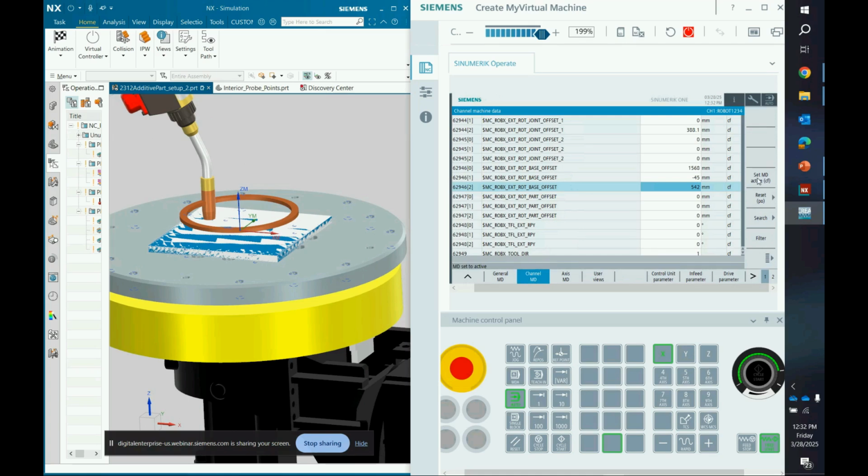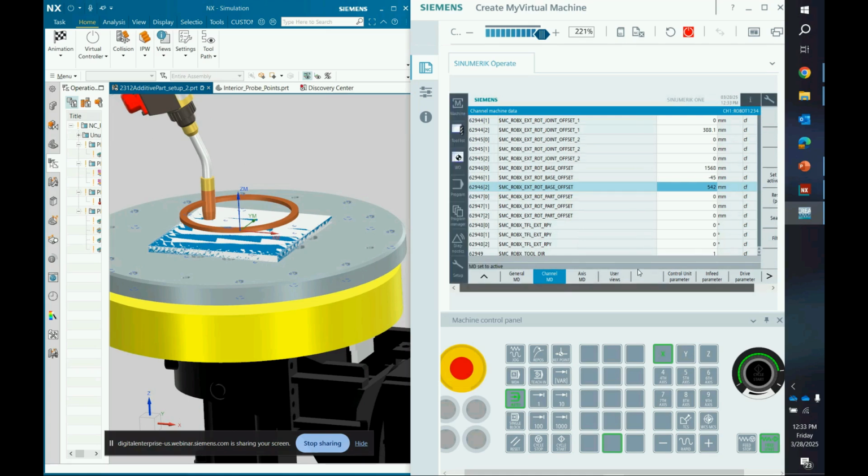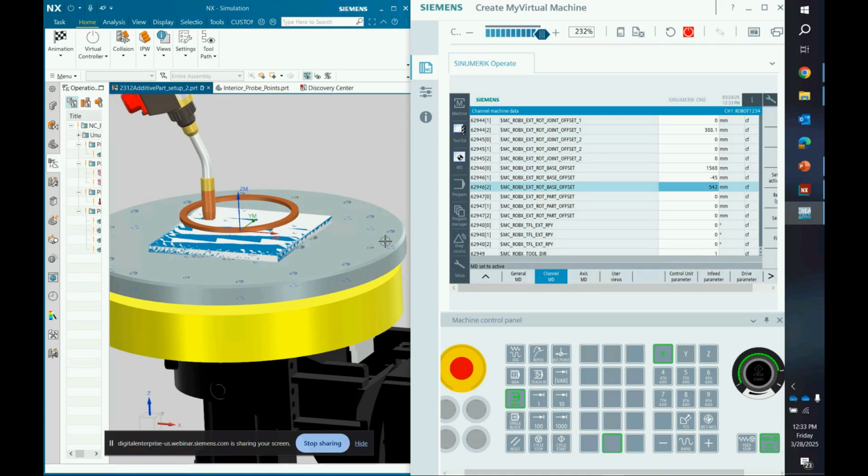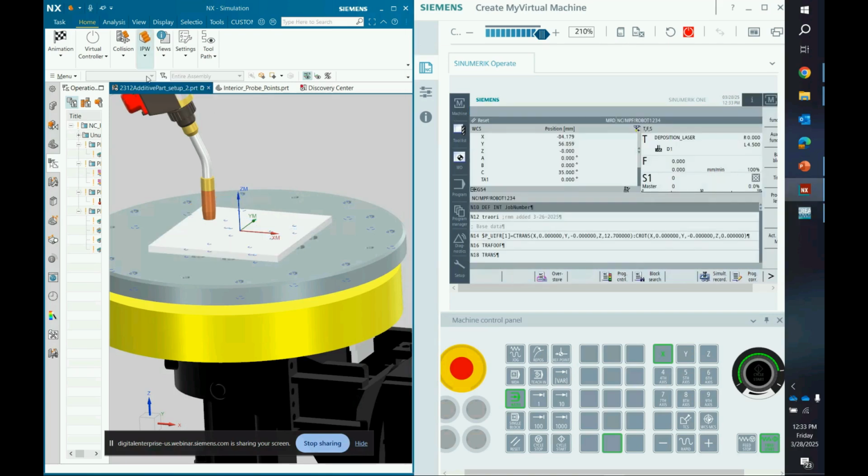And we can do that. We can validate part programs, validate controller data, validate exactly how our digital system is set up, all digitally, without having to walk back and forth, posting from CAD CAM, walking out to the machine, loading it, running it on the real machine. Hey, there's an error, walk back to the CAM office, right? We're doing all of this digitally. So I can reset here.